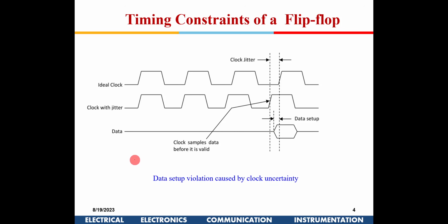Okay, so can I say that a clock coming early into the capture flip-flop, where the data needs to be captured, will cause setup violation? Yes, sir. So a clock which is coming early into the capture flop can cause setup violations.